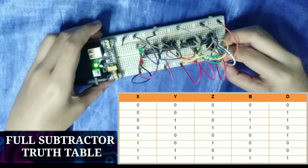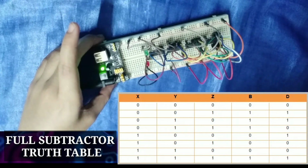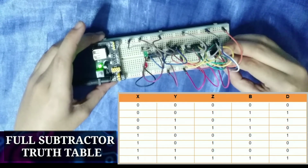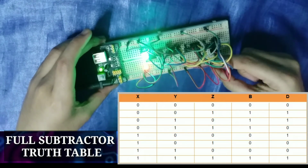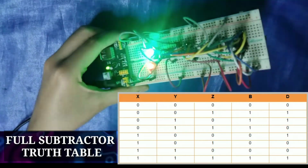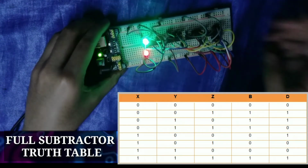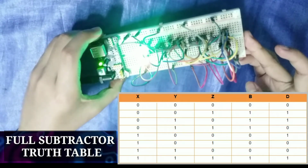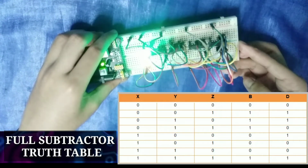As you can see, both of the outputs B and D were turned off. Now, if all of the inputs X, Y, and Z are connected to the voltage supply, both the D and the B outputs, or the green and the red LED, were both turned on. So that's our truth table for our last logic diagram circuit, which is our full subtractor circuit.